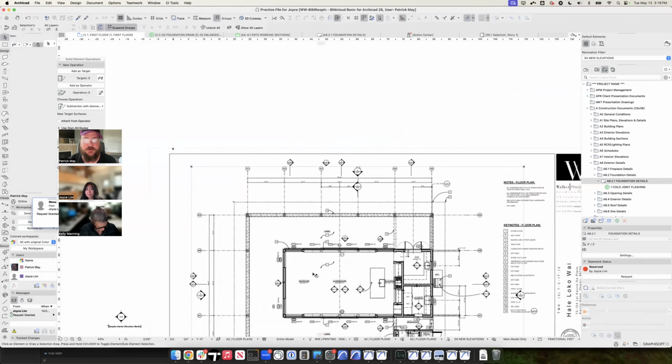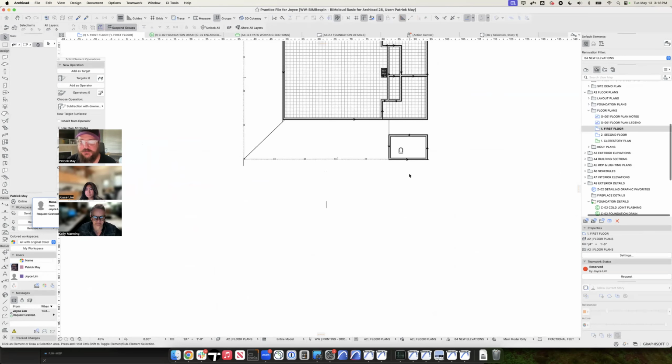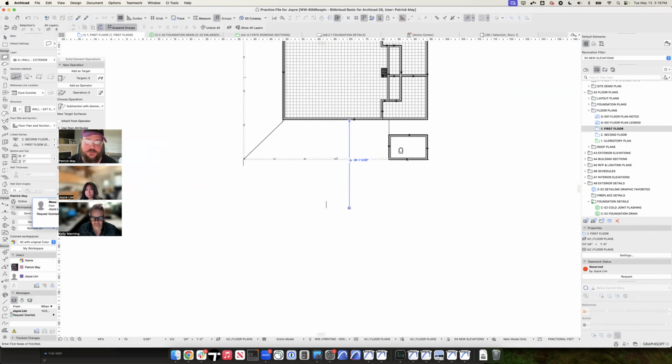One thing to remember, and I say this because when I learned ArchiCAD 20 some years ago, I had been working for the better part of like 3 days before I went to my boss, and I said, "How do I make a wall that's exactly a set distance?" Because I was just sitting here going, "Well, that's about 12 feet, right?" Oh, yeah. Don't forget to hold shift. That's going to lock to that axis, so it's not accidentally snapping to like 0.0001 degrees.